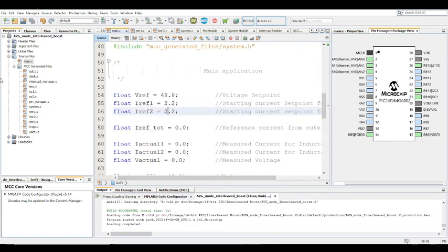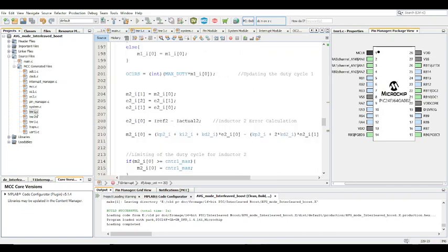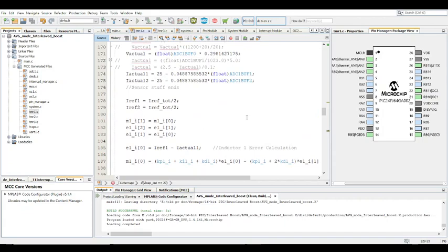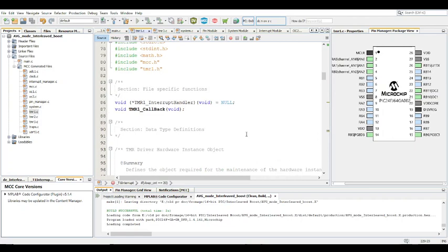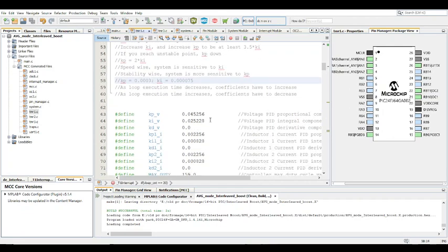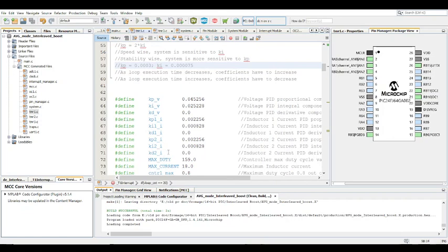So essentially that's what you want to do, right? You want to test the inner loop first, and once you see that the inductors get to the set point, obviously you design your system in such a way you can check the current flowing through the inductors independently, like a piece of wire where you could easily clip a current clamp around it and check what's going through the inductors. And you want to check the inner loop separately doing that, and make sure the control coefficients are proper. Obviously you should always start with this coefficient, kp equals to, it won't be fast, it'll be quite slow, but it gives you a start. And obviously there are different coefficients for both of them. You could use the same, but I'm just trying to be careful and conservative. This is a definition of the coefficients: kp, ki, kd. This is for the first inductor, this is the second inductor.